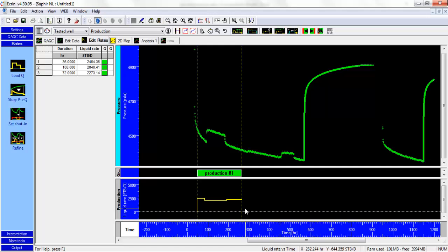You can use simply the rates based on this pressure, the flowing pressure. You can see that now probably for this time period we've got more or less the same rate as this one. Now we've got the choke back. Maybe this period will be the same rate as this one, so probably this one. Rate of 0 for the PBU. Now we've got a gap of data.